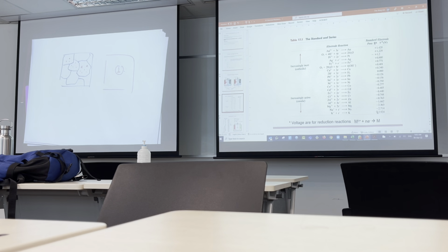When attacked, people figure out and tell you, oh, I have this amount of dislocation inside. How do they do it? They actually etch it and just count how many of these pits suddenly appear. These are attributed to dislocations, and they give you an idea. This is the dislocation density.